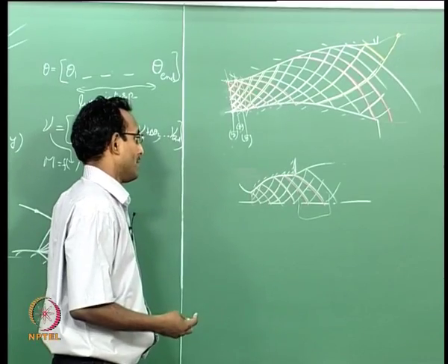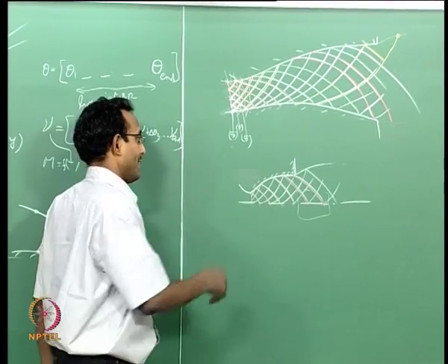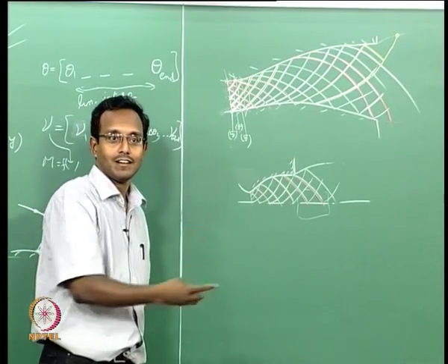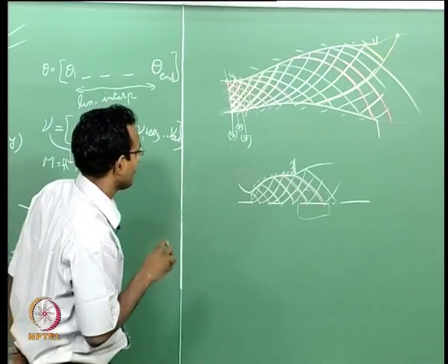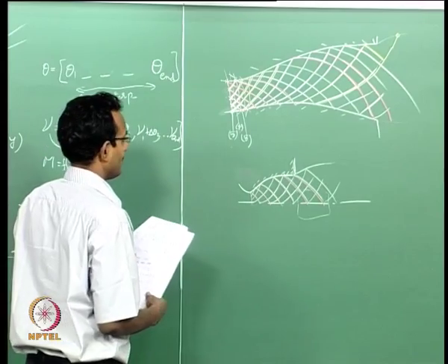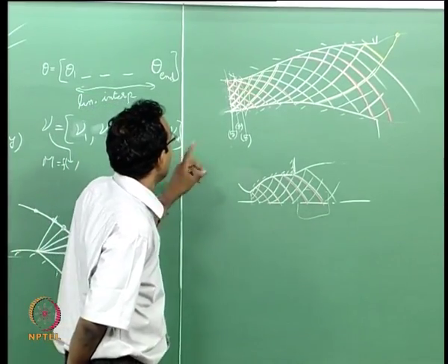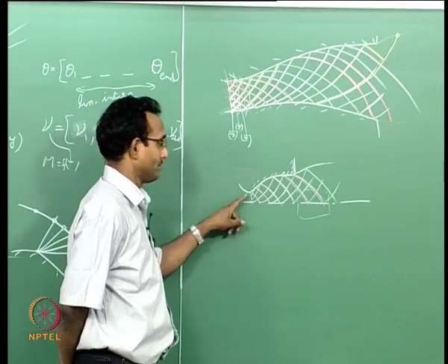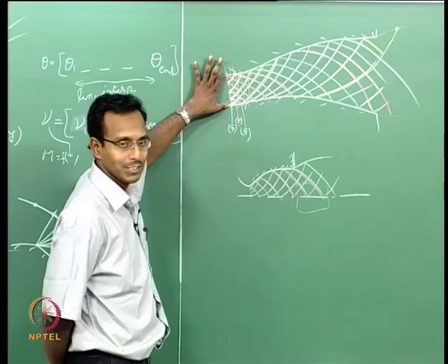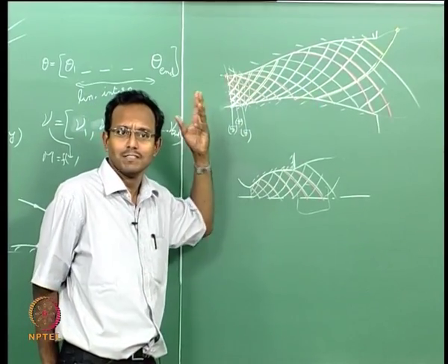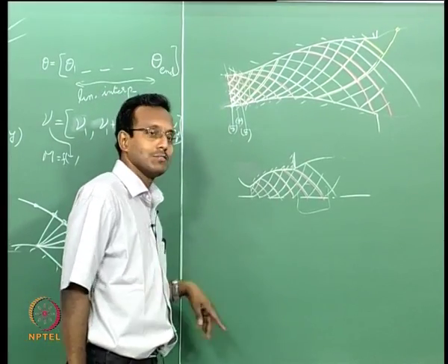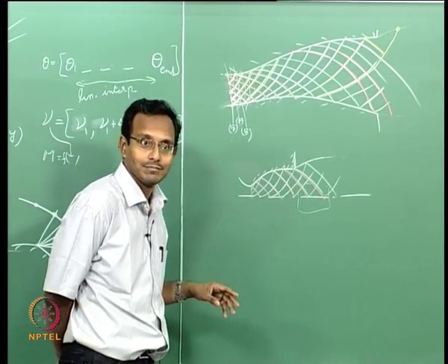Okay. Typically, if you are just writing flow through a nozzle, I would say go towards axis, that is right running characteristic typically, if you are solving for the top half. Okay. That is one way of looking at this. Now in all this, we needed this initial set of data points. Of course, there will be problems where we will be given the initial flow condition and then we have to solve from there. That is simple, there is no more trouble there, I can just put how many ever points I feel like there. But there will be times when nobody knows what the data is.